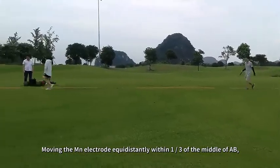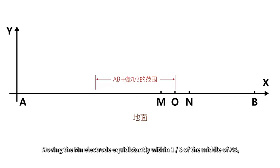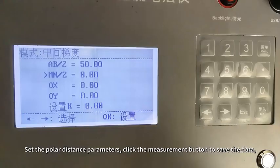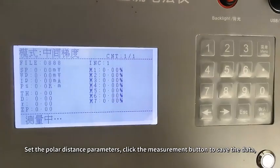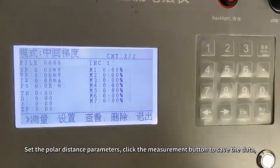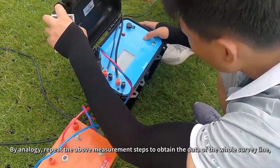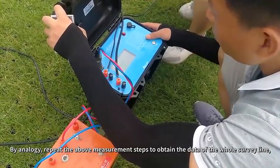Move the MN electrode equidistantly within 1/3 of the middle of AB. Set the polar distance parameters. Click the measurement button to save the data. By analogy, repeat the above measurement steps to obtain the data of the whole survey line.